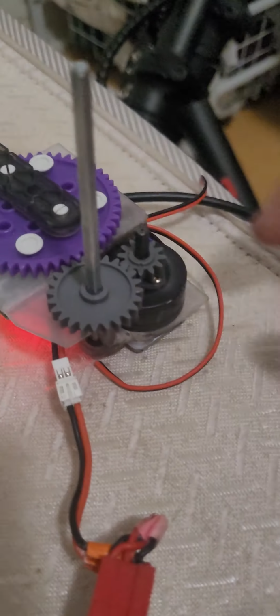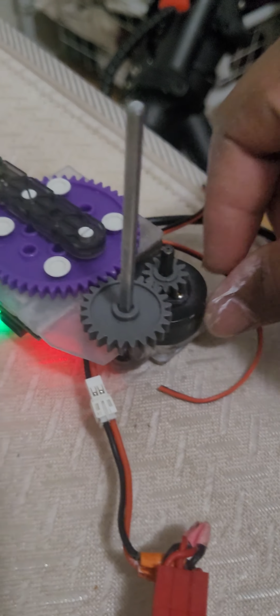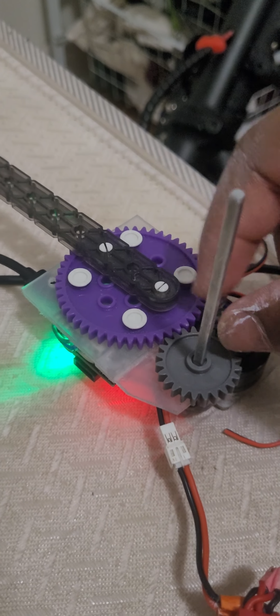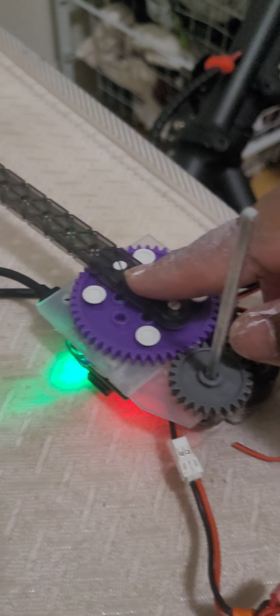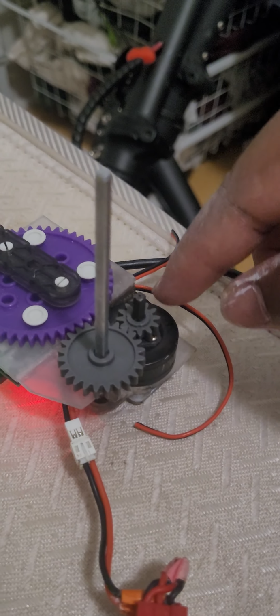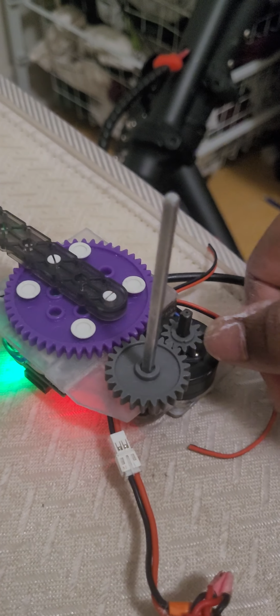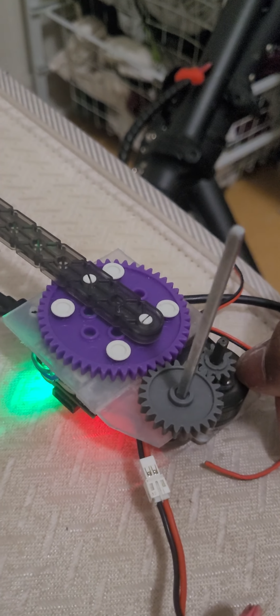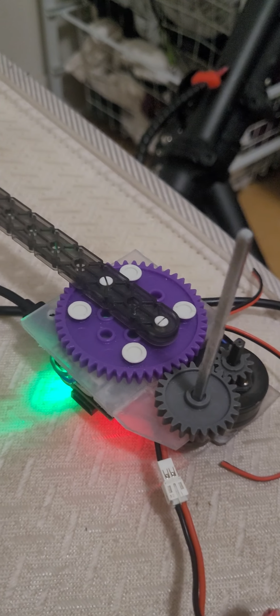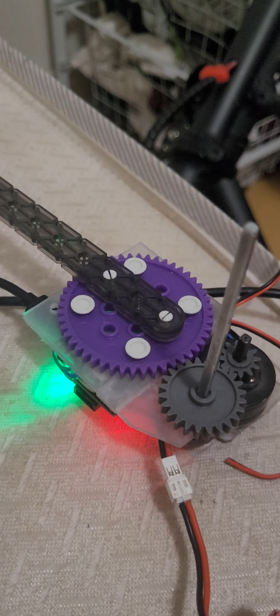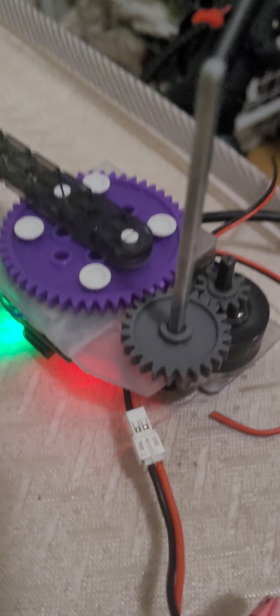The thing is, it's not going to give me full torque, considering the fact that I ran this motor through the wringer. I did a bunch of stall tests and everything, and this thing got really hot. It even burned my finger. It got so hot that the magnets inside got demagnetized, because when neodymium magnets come under heat, the structure changes and the magnetic effect weakens. So, that's why you spend money on random stuff.